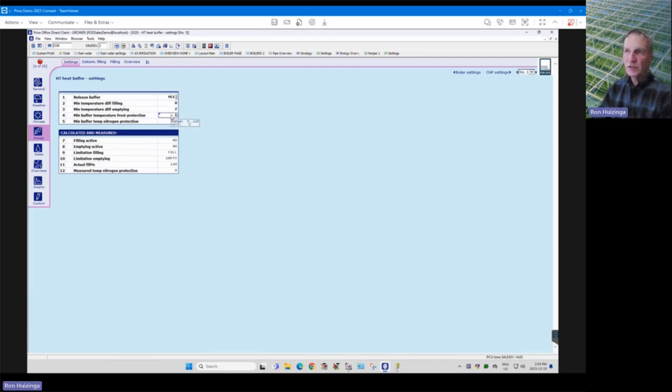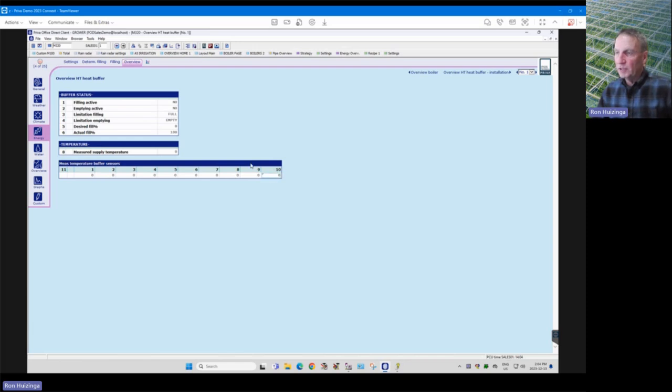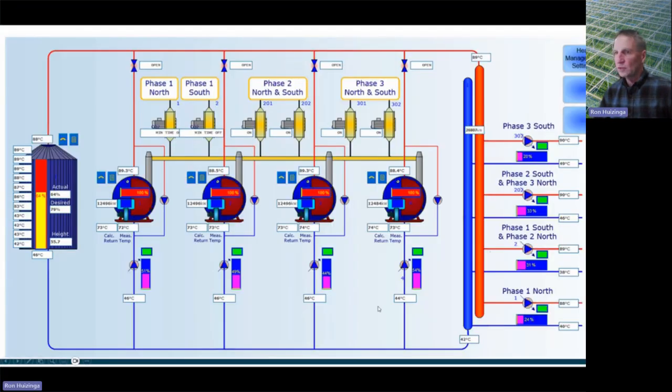There is a frost protection on the tank, so if any sensor gets below 1 Celsius, it gives you an alarm. That means that obviously something has drastically gone wrong, because if the tank is completely full, it's all 90, but even if it's empty, and if I go to that other screenshot here, these sensors are all the typically cold sensors, but you can see that cold is even 42 Celsius, which is around 105 to 110 Fahrenheit.